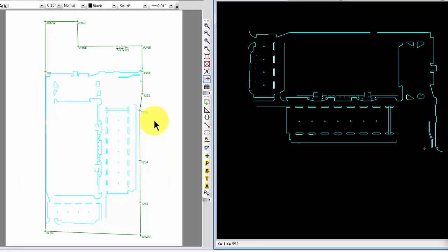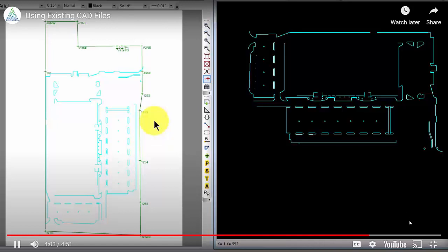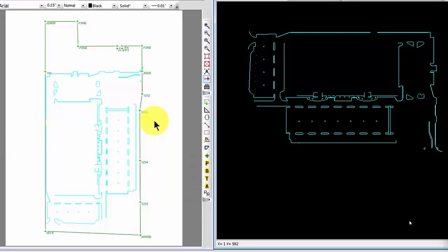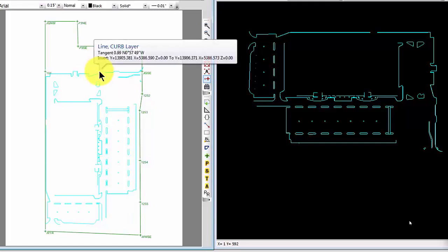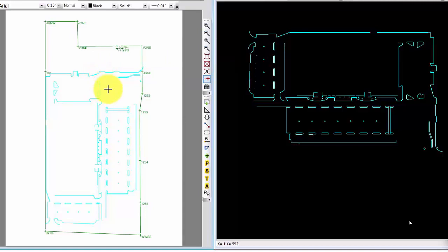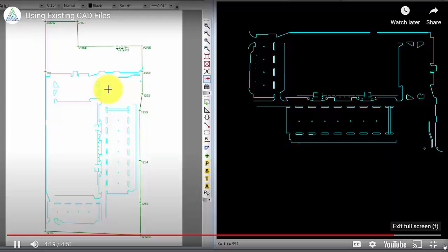So now they are oriented the same way as the drawing in the drawing view. They are on this curb layer, same layer they were on in the CAD view. But now I can come in and convert to survey or pull additional information out of these for use in COGO or in another drawing or in putting a billing together for the work that I did.